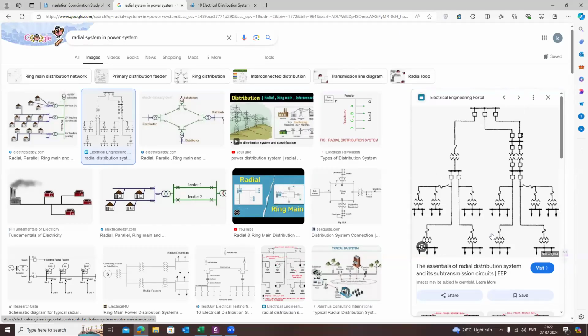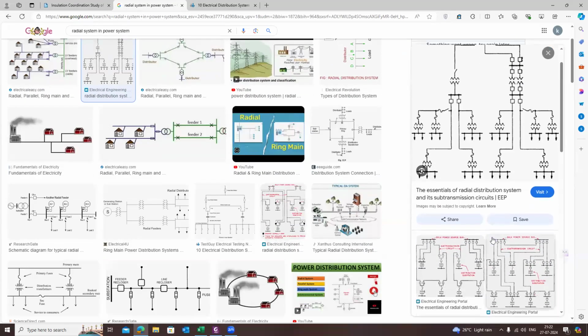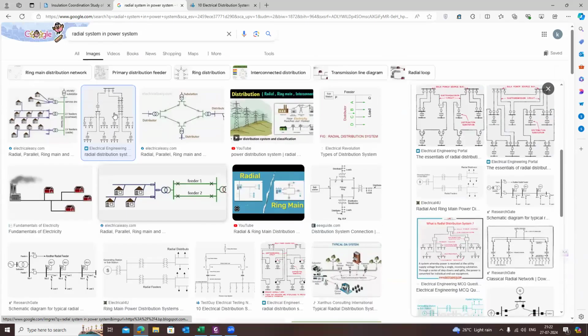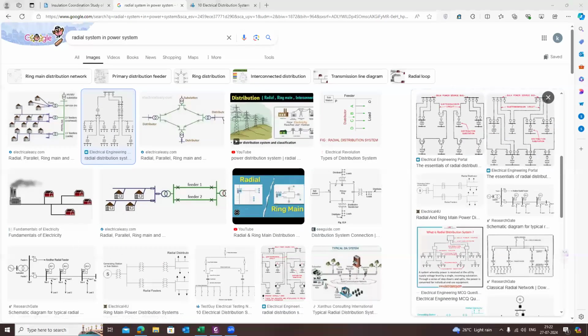So it is a very simple addition itself. And of course, that's a vectorial addition, because the power factor of the two different loads will be different. But nominally, a numerical addition is enough to find out the equipment loading in the radial system. Whereas that is not possible in interconnected systems. Let me take a snip of this to show it better.